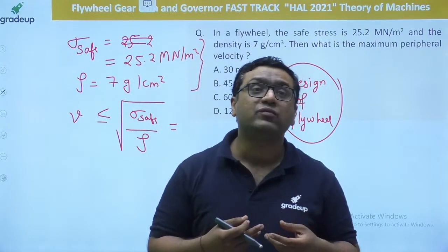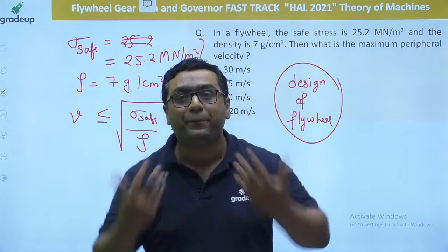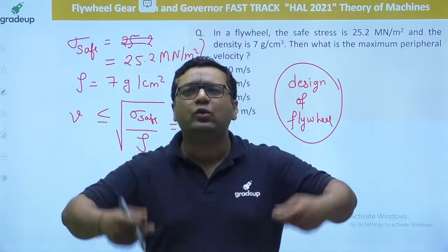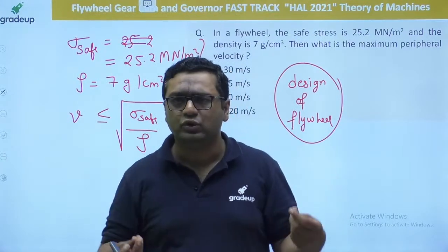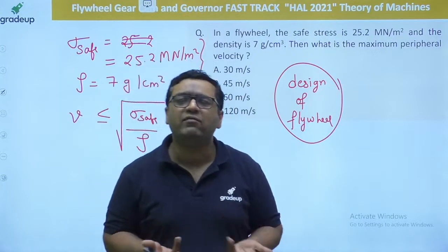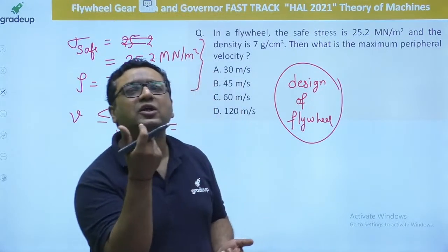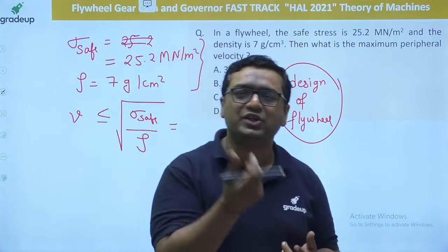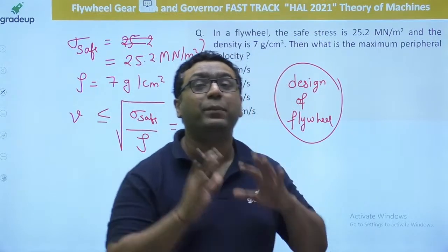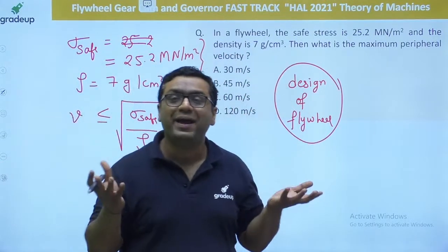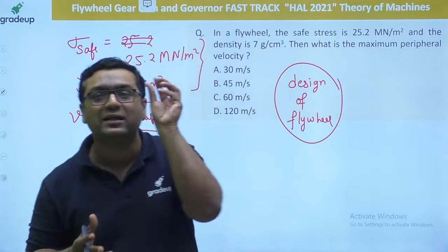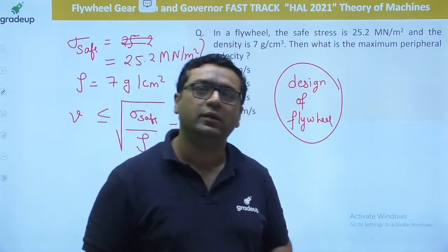But in a gearbox, the gear is going to provide the power throughout, so you need to have that power to be used. So a flywheel is not required there. A flywheel is required where energy is needed only in a small part of the cycle. The complete energy given by the engine will be supplied at some very small interval.